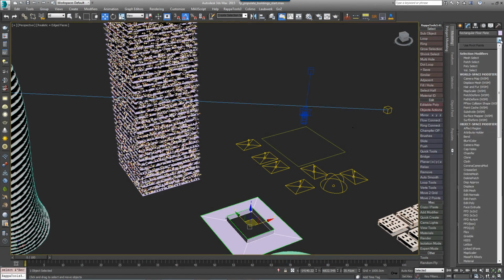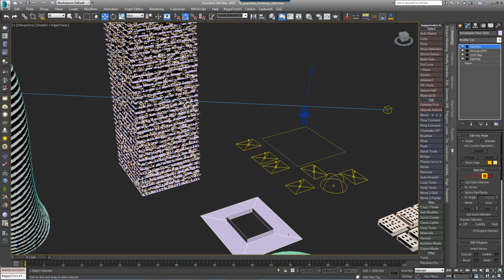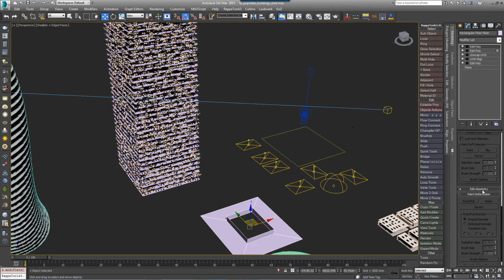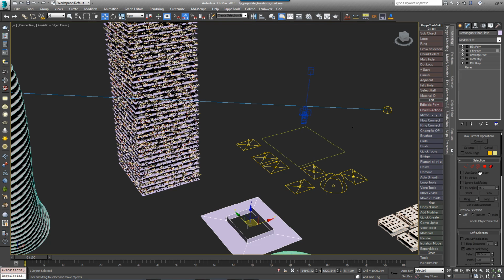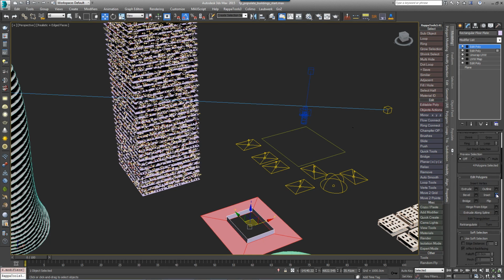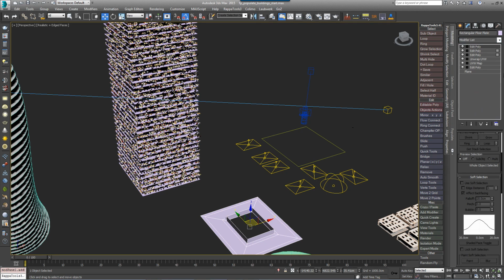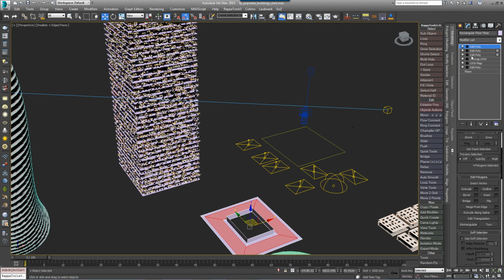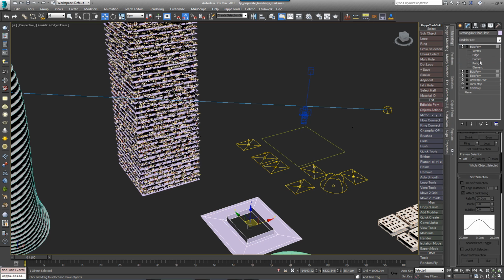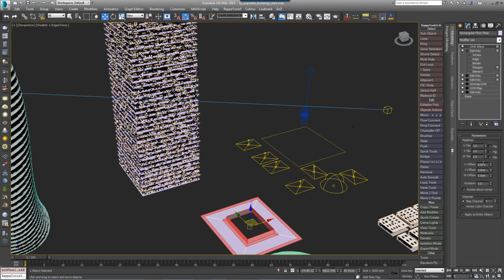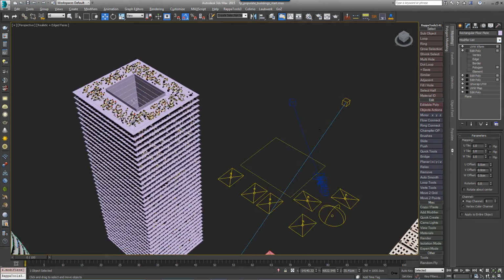When preventing objects from penetrating the facade, we're still using UV mode, so the best way to control the scatter is using the distribution map as we described earlier. The only real difference is that now we only need to edit a single floor, because RailClone will duplicate the geometry for every level. This also explains why we make the white area of the distribution map extend well beyond the 0 to 1 UV space. If we didn't, the UVW Xform randomization effect could cause unwanted black areas to appear in the distribution map.